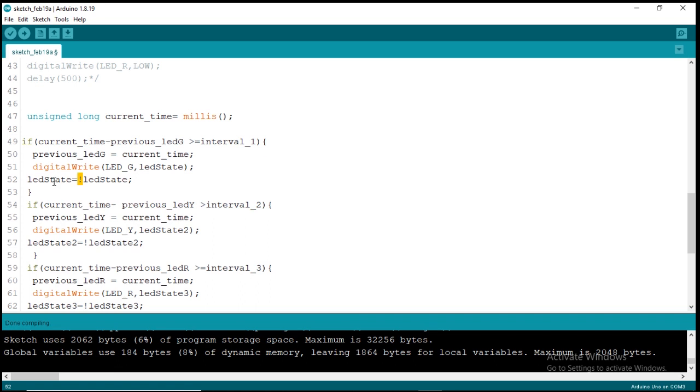This LED state, which is 0, we now invert it to 1. So whenever this recycles again, it will come here and see 1 instead of 0. That is the reason it is blinking, because at each cycle it repeats itself. It will be seeing a different state. If this is 0 state, whenever the compiler recycles again, it will see it as 1.